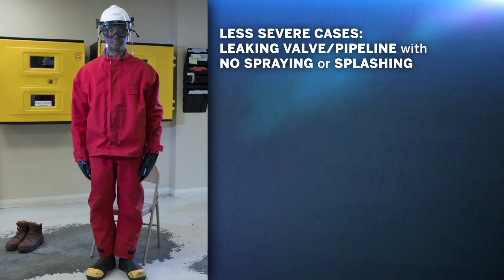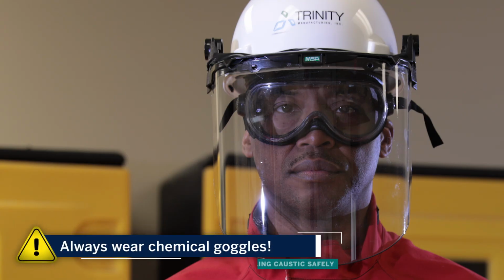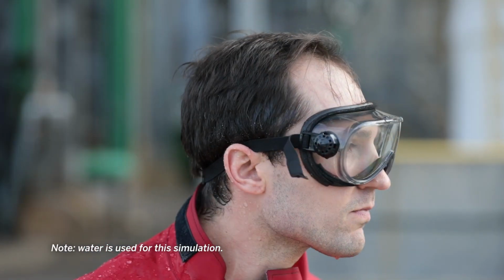In less severe cases, such as a leaking valve or pipeline with no appreciable spraying and/or splashing product, respiratory protection may not be needed. This recommendation is based on the assumption that, unless otherwise determined by the incident commander, the responders to a sodium or potassium hydroxide release will not be exposed to concentrations in excess of 2 mg per cubic meter in any 15-minute period. It is very important that chemical goggles are always worn, even when using a face shield. There is a natural tendency to turn the head quickly when sprayed in the face, exposing the side of the face and eyes if not protected.